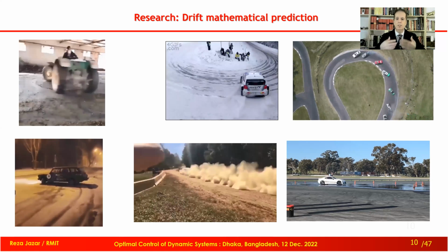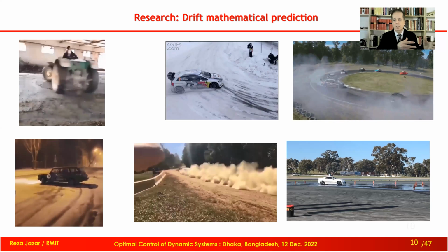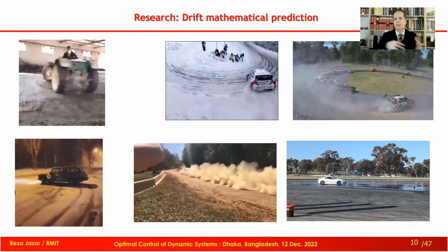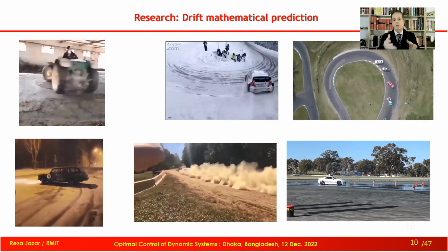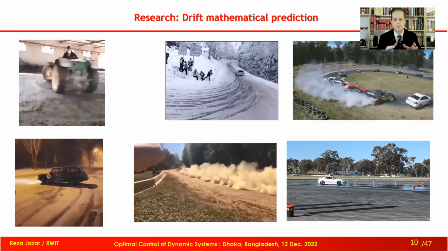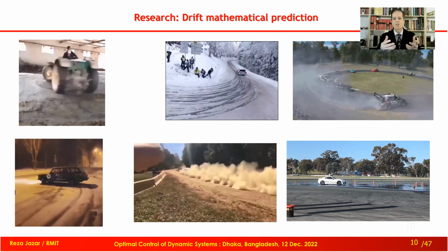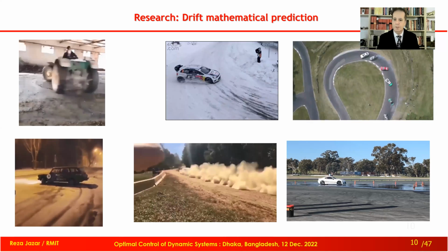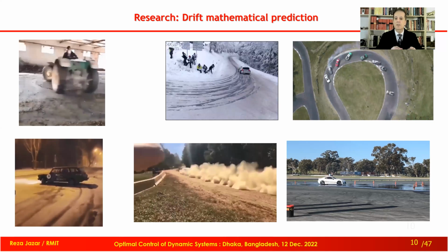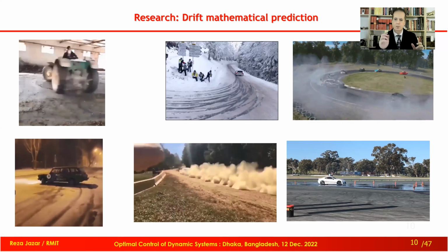So when this equation, which is related to some kinematics information coming from a vehicle that we can measure by sensors, has every variable put in and we measure the resultant, and when it is getting close to zero, we are getting close to drift, and there is a warning system in the vehicle connected to a computer, like ABS, that takes the control from the driver and acts to prevent the wheels from getting locked during braking.